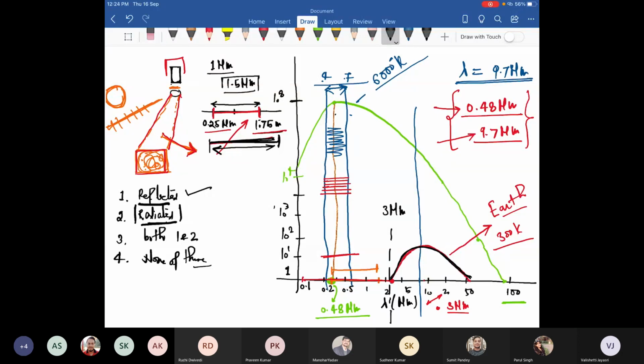So this is the 3 micrometer dividing line, after which, at wavelengths more than 3 micrometer, Earth starts radiating energy. And the radiated energy keeps on increasing till 9.7 micrometer. So we achieve the peak at 9.7, and further with the increase in wavelength, it will decline, and at around 50 micrometer, it will be 0. So we have the available radiated component only between 3 micrometer to 50 micrometer, where the peak will be at 9.7. Got it?